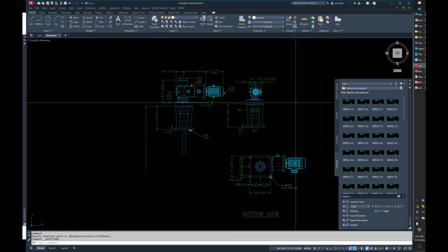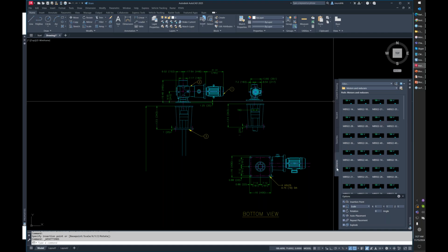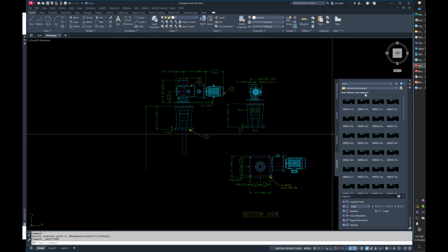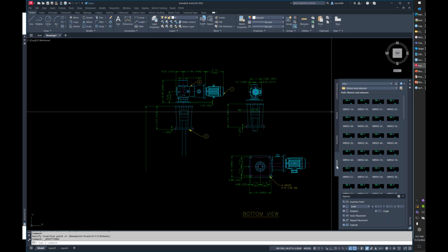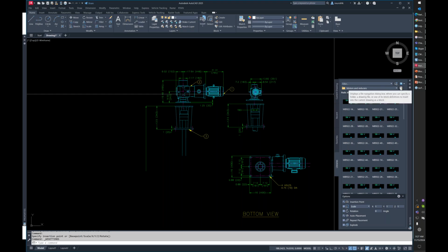Right? So this is using the block library. Only the filter. What version of AutoCAD are you using, Kathy? Because you may be missing an update. If you have the block palette and do not have everything for the block library, if you are missing this piece right here, 2022 Civil 3D, you should have this right here. If you don't have this, we may need to repair your Civil 3D. We can talk about that.